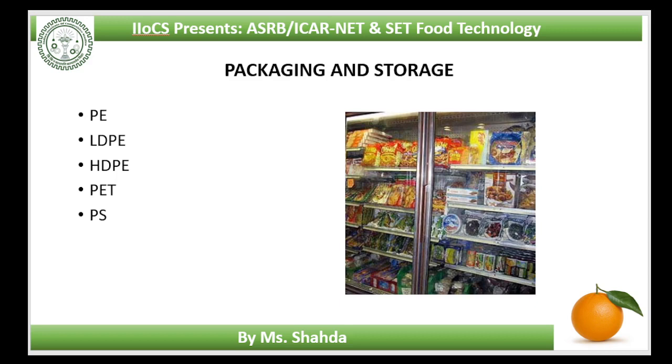A wide variety of materials have been used for packaging of frozen foods, including plastics, metals, and paperboards. Polyethylene (PE), low-density polyethylene, and high-density polyethylene are commonly used for packaging of foods such as fruits and vegetables and fish. Materials are easy to seal and can be easily printed. LDPE is also easily available and cheap. HDPE can tolerate temperatures in excess of 100 degrees Celsius. Both HDPE and LDPE, however, provide relatively poor barrier protection from oxygen.